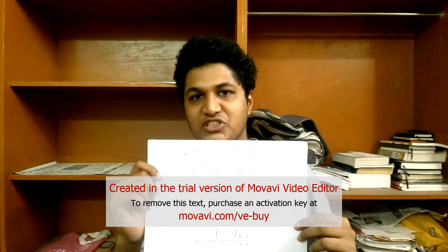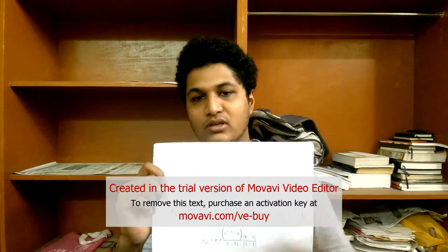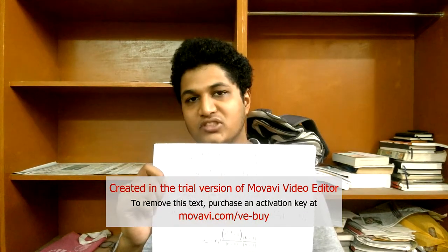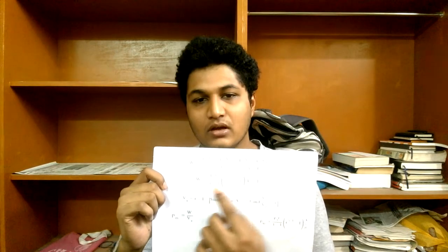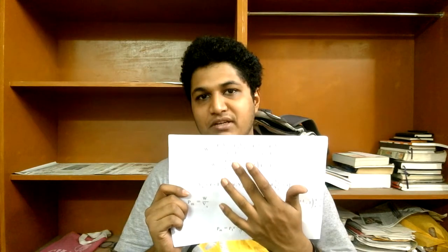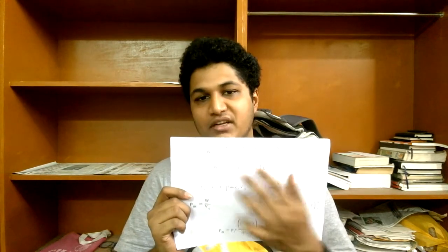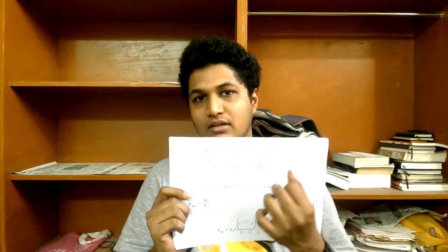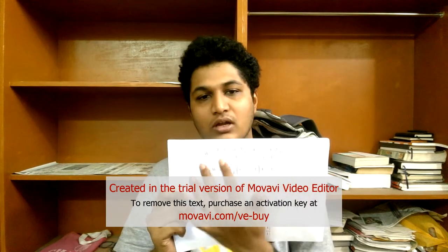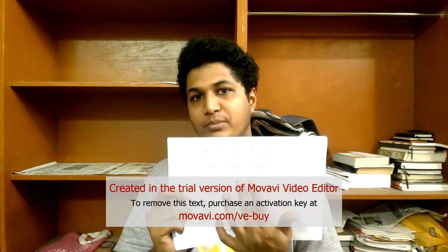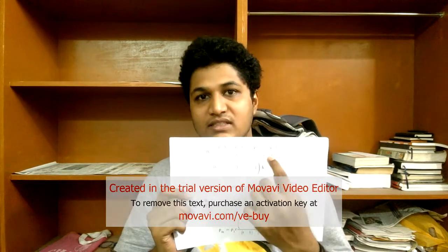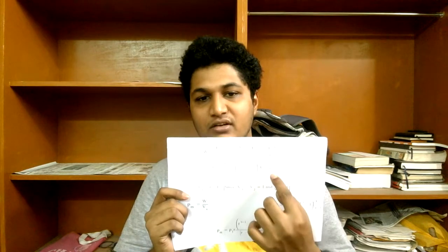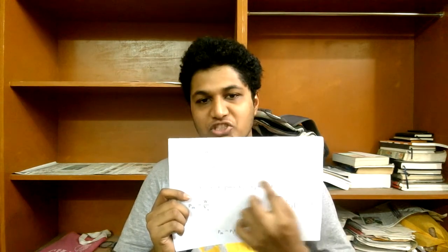We'll go over these equations one by one so that it becomes clearer to everyone. Work done for an isentropic process is given as P1 V1 minus P2 V2 over gamma minus 1, and we have expanded on that here. Work is being done as positive in one process and negative in the other, so you have to consider both cases. The net work done will be W1 to 2 plus W3 to 4, and its sum can be written in terms of pressure and volume, and then in terms of pressure ratios and compression ratios, which is this equation over here.